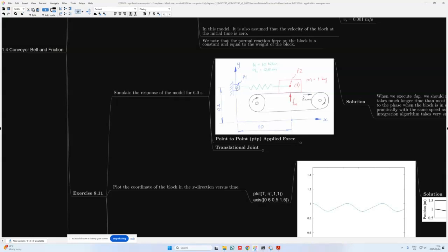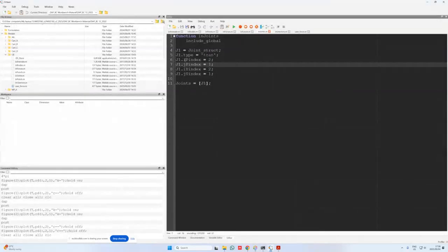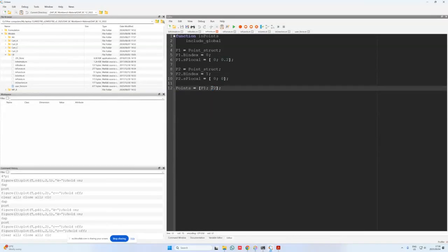So I'm going to define my JP index as point 1 and my IP index as point 2 in this case. So then vector D is constructed from point 1 to point 2. Now, if I look back over here, IP index is indeed 2. If I go over here, I can see that corresponds to P2, which is then defined on body 1.